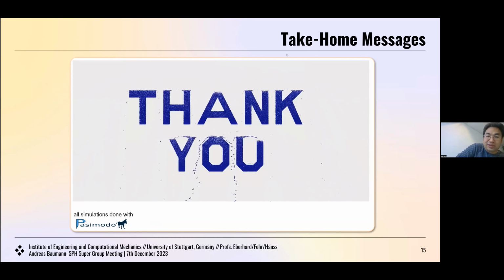We have the finite element code, which is separate from the SPH code, exchanging position and forces back and forth. Therefore, we use the functional mockup interface, which is an industry standard for co-simulation. It defines interfaces for exchanging data from one simulation to another, and also bundles the finite element code nicely so it can be imported into our SPH simulation.